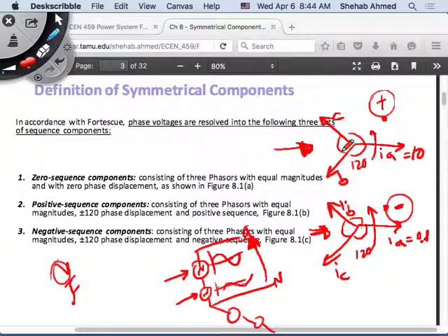It will decrease the motor torque on the shaft, but the current that produced the positive torque will be there. The current that produced the negative torque will be there. So I actually have more current, but I have less torque. What does that do to the motor? Any machine, if you have more current but less torque than what you're supposed to get, will just heat up.